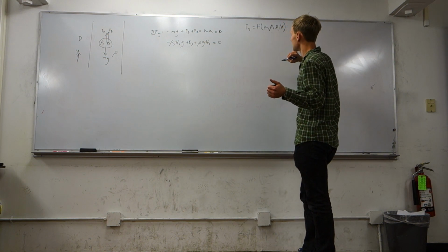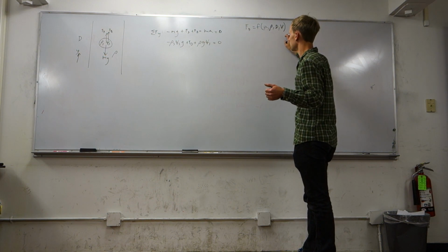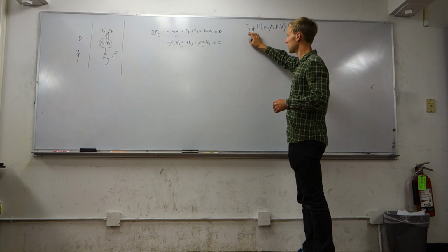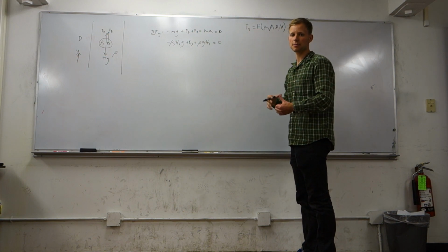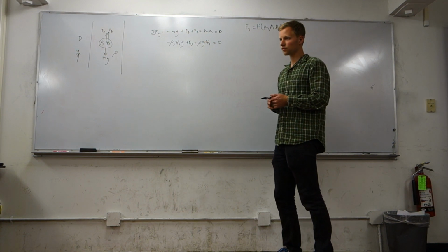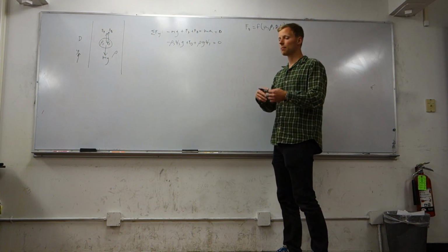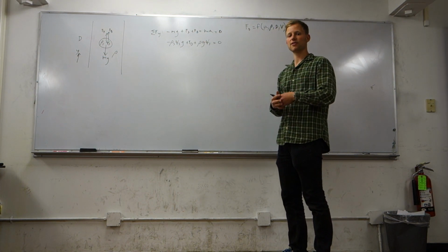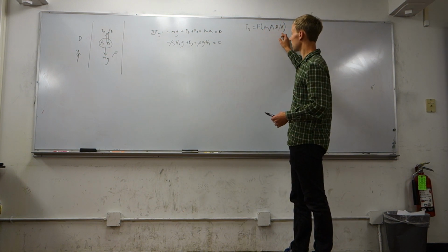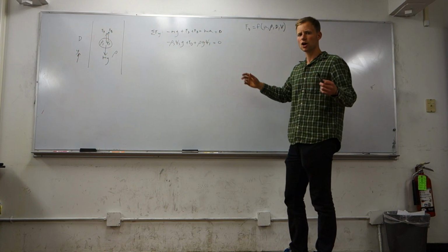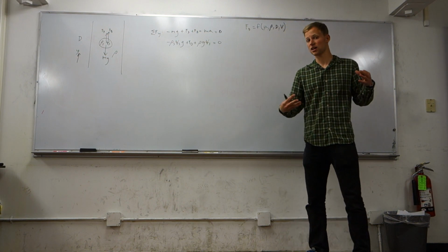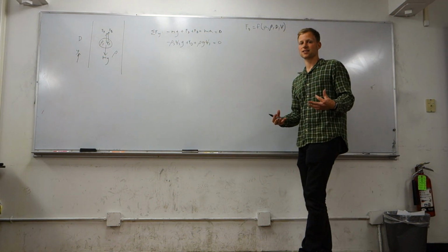So this is sort of our first guess at what the drag force might depend upon. And this is a lot of parameters. What we want to do is find the drag force using fewer parameters and make it a more general problem. So if I were in the business of measuring drag forces, I could make a bunch of spheres and put them in a bunch of different fluids with different densities and viscosities and subject them to different velocities. And I could hold each one of these things constant and vary one variable, and I'd have a bunch of different relationships between drag force and viscosity, and drag force and density, and drag force and velocity. And that seems like a hassle.